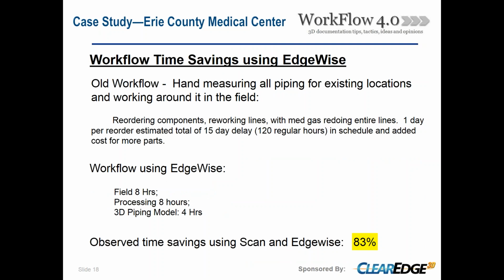If we were going to do this the old way, hand measuring all the piping for existing locations, having them work around it in the field, having them reorder components, rework lines. Med gas is a big deal in healthcare. If you have to redo med gas because it's not coordinated, it takes a lot of extra time because the lines are sanitized. So we were able to say about 1 day per reorder, estimated total of 15-day delay, or 120 regular hours in the schedule and added cost for more parts.